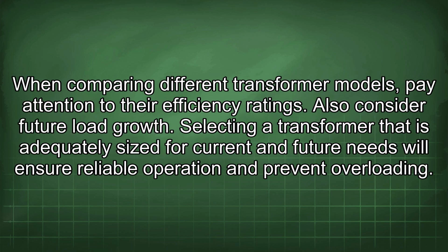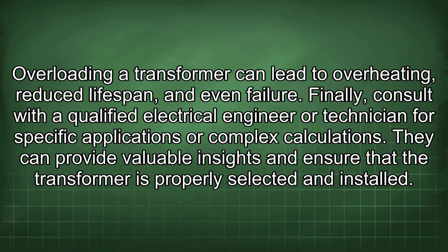When comparing different transformer models, pay attention to their efficiency ratings. Also consider future load growth. Selecting a transformer that is adequately sized for current and future needs will ensure reliable operation and prevent overloading. Overloading a transformer can lead to overheating, reduced lifespan, and even failure. Finally, consult with a qualified electrical engineer or technician for specific applications or complex calculations. They can provide valuable insights and ensure that the transformer is properly selected and installed.